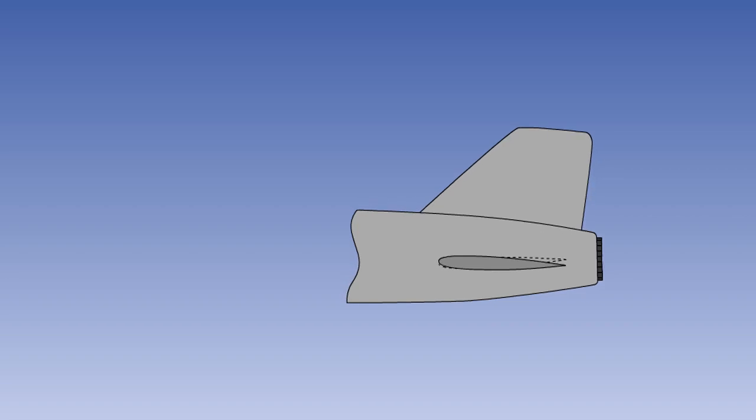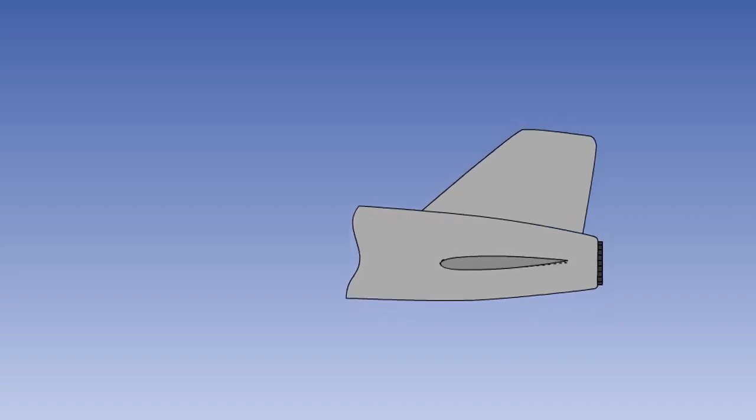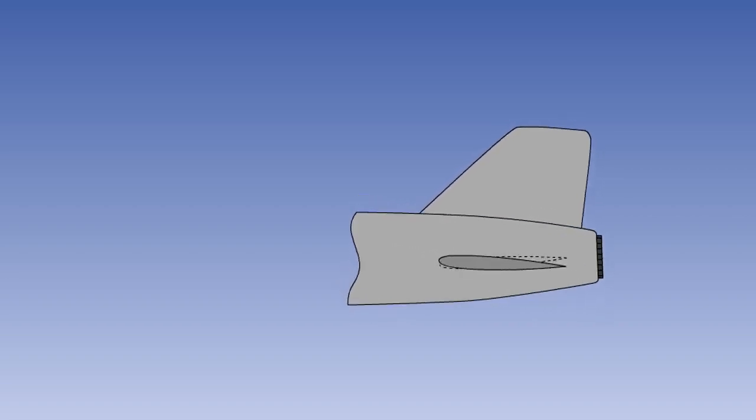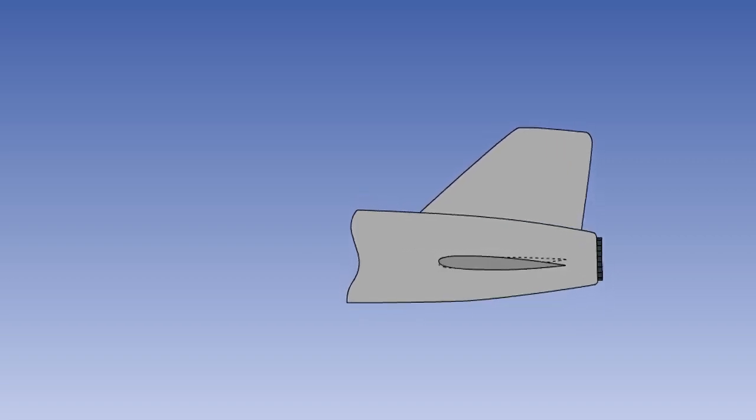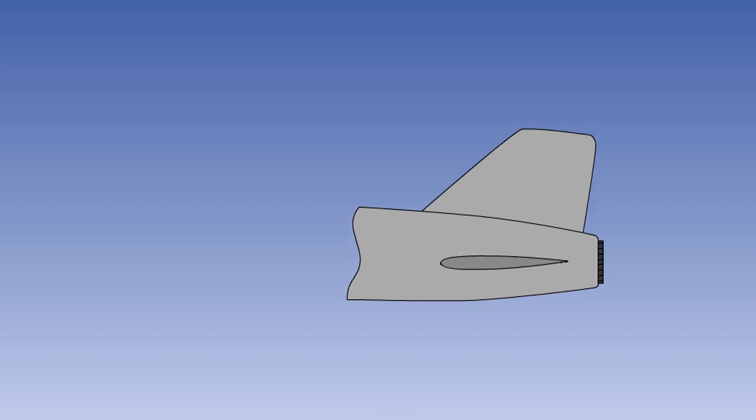Varying the incidence, and hence the angle of attack of an aerofoil, will also vary its lift. This system is often used instead of elevators for pitch control. The whole of the tailplane or stabilizer is rotated to vary its angle of attack.